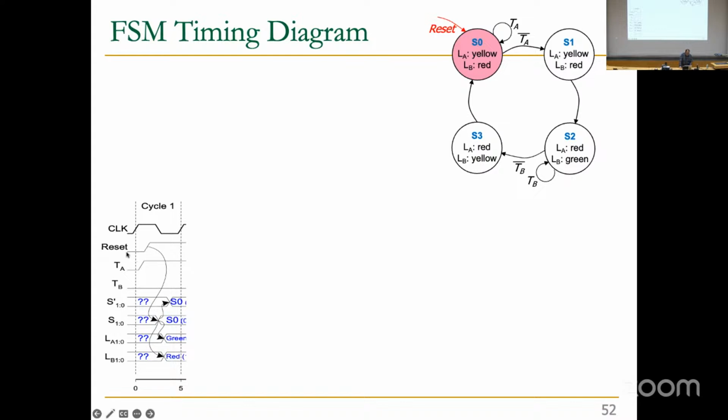So you can see that when we activate the reset signal, the current state gets to 0 after some delay. It doesn't wait for the clock signal. You can see that here we consider some delay, and that's actually the case in real life. First of all, clock signals are not that sharp. They are usually like this. There is a rising edge which is not completely sharp. The same thing applies for reset and for other inputs.